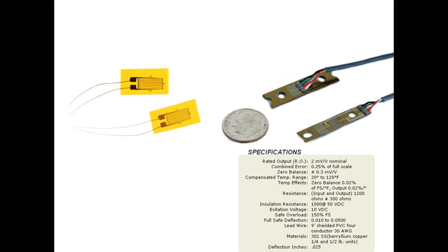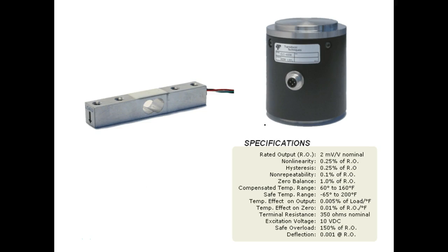Then you take 4 of them and put them in the weigh bridge. You put one in each corner, and then of course the weight was distributed over it. So 4 80,000 pound load cells would give us the ability to weigh what, 320,000 pounds. So we had truck scales. We worked on a lot of the truck scales that the Alabama State Highway Department uses to measure the trucks when they come in, to make sure they're not running heavy. Buy and sell off of.